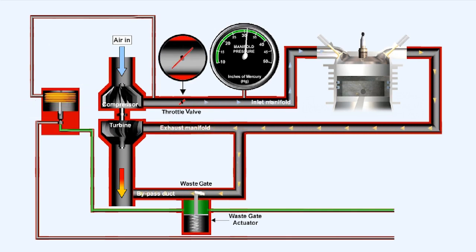Coarse use of the throttle may cause a phenomenon called throttle sensitivity to occur. Throttle sensitivity is a result of a chain of events which can occur as a result of change of throttle position. Let's imagine what might happen if the pilot opens the throttle in a simple system with an absolute pressure controller like the one just described.